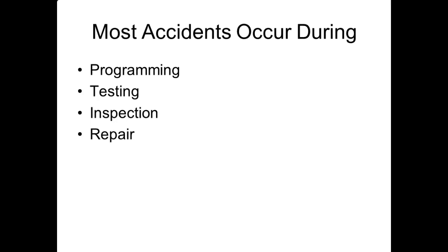Now, some of these robots support what we call a high-speed teach. The KUKA supports a high-speed teach. The Big ABB supports a high-speed teach. That doesn't mean when you're jogging the robot, it's when you're testing the program out. So we have the ability to test the program without switching it into automatic mode. If the robot supports a high-speed teach, then it can run at the speed of production. If you're in the work cell on these robots and you run it on high-speed teach, you'll get in trouble.